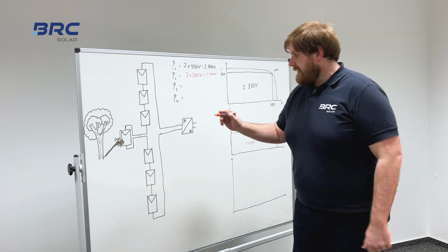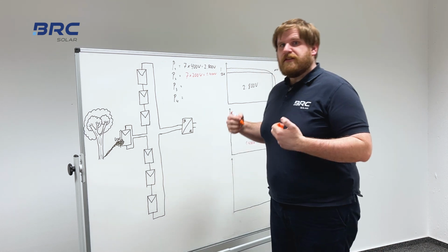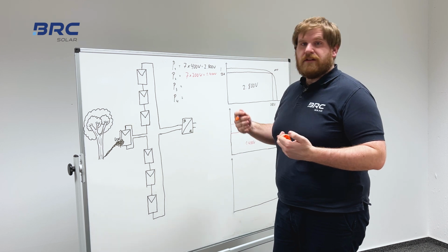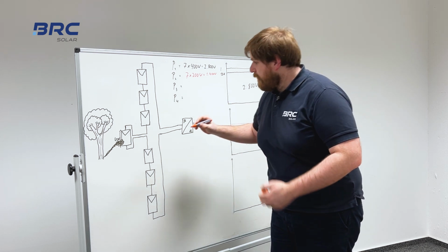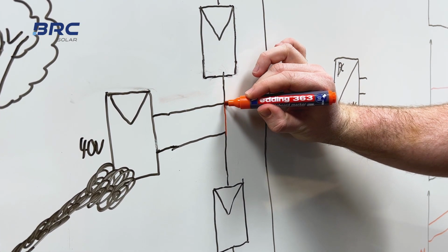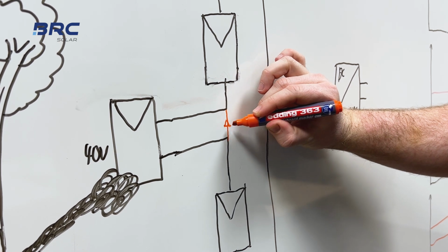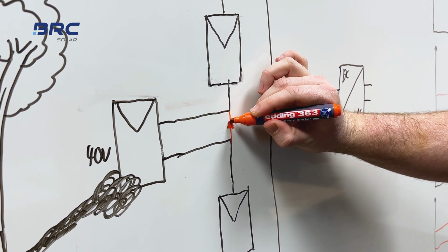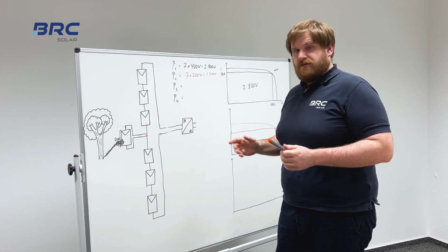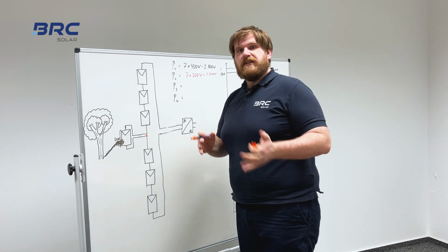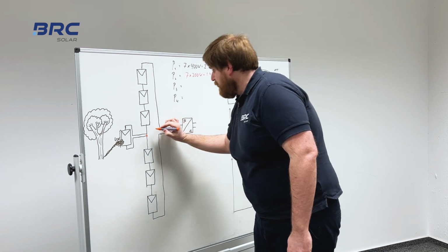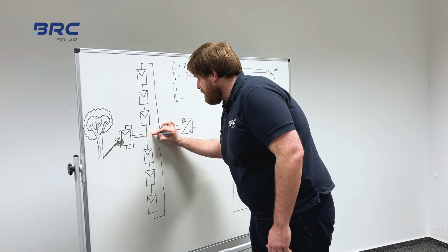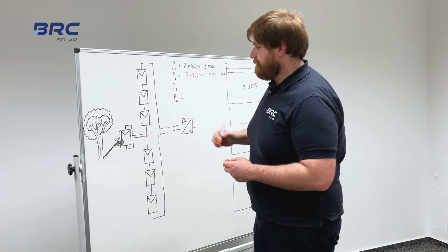So in that case, the inverter would increase the current even more than these 5 amps, and this one module would get bridged out of the system by a bypass diode. Now this one module produces no energy for the string any longer. We have 0 watts from this module.